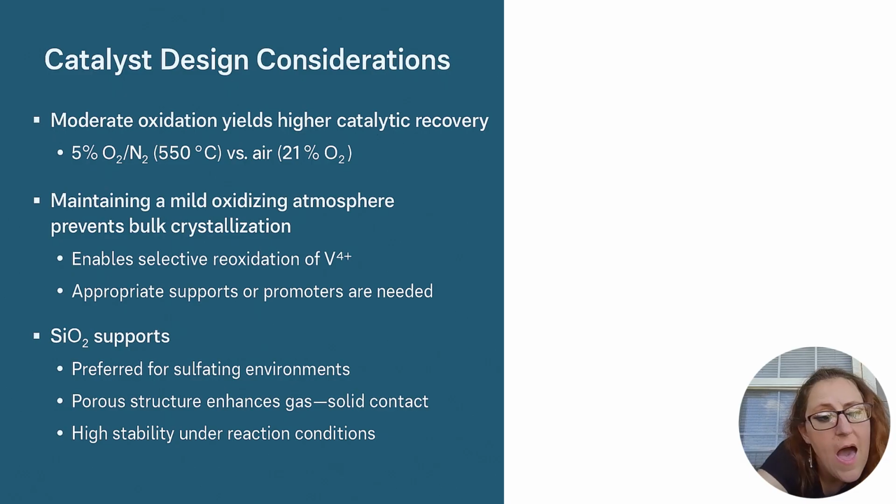phase. Alkali metal promoters such as potassium sulfate, sodium sulfate, or cesium sulfate lower the melting point of the vanadate mixture to create a mobile molten catalytic phase active between 400 to 600 degrees Celsius. There are also optional additives like potassium hydrosulfate or cesium hydrosulfate, which stabilize the molten pyrosulfate environment and facilitate the redox cycle.